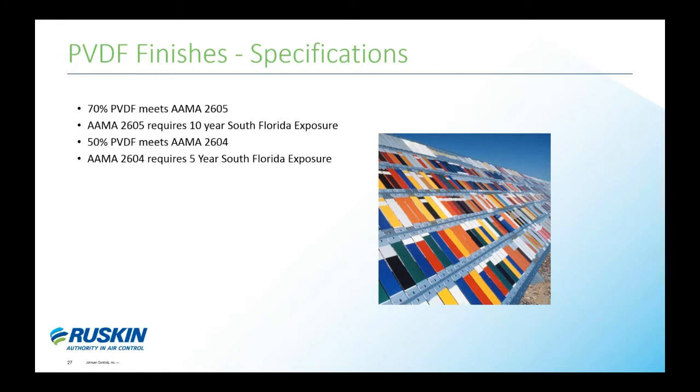The AAMA 2605 specification requires a minimum of 10 years of exposure at a 45-degree angle in South Florida at a 27-degree latitude. These finishes offer superior protection against the elements and are offered in virtually any color required on the project, predominantly as a color match.